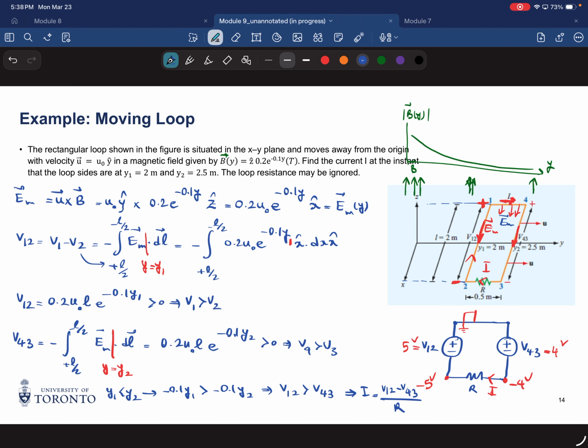The voltage difference makes this possible because you have two sources that are different in size. The only way to make these two connected to each other is to connect them with a resistance, so you can have a current carrying that voltage difference. If the resistor wasn't there, then immediately you would have lots of current going from one source to another, basically short-circuiting.